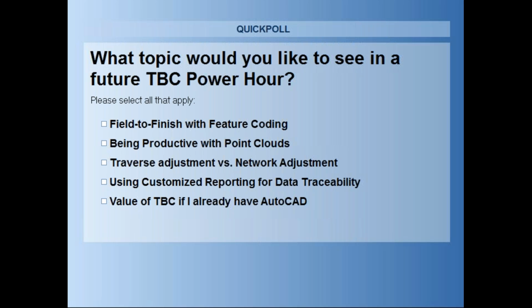Another question, Brent asked, can the labels you created in drafting be included in the diagram of the lot closure report? Yes, they can. So you noticed in the second page of the lot closure report, there is a diagram of the lot itself with the grid lines. Any annotation you make on that lot will actually show up in that plot as well, which is kind of a neat feature. Yeah, I didn't show it. I didn't do all that first, but it will show all your labeling on that report as well.